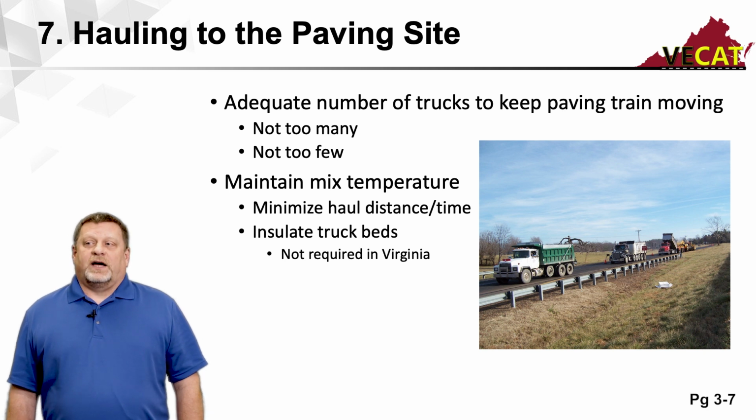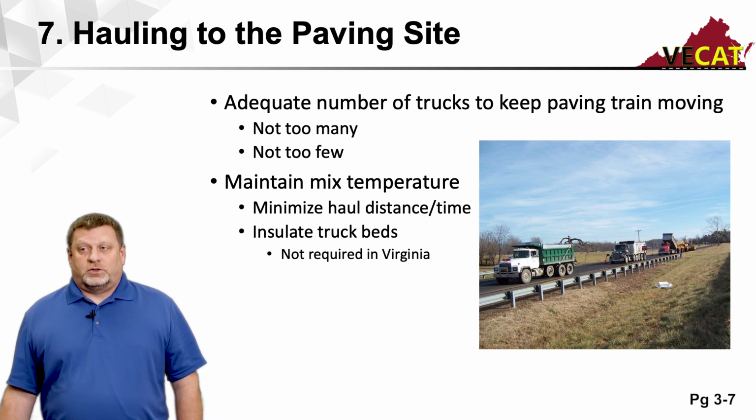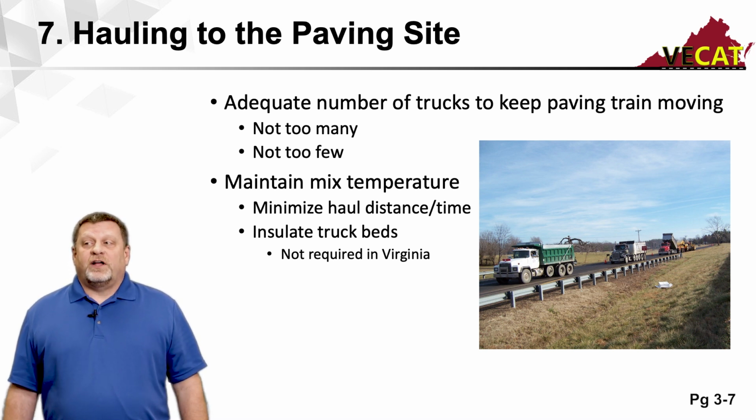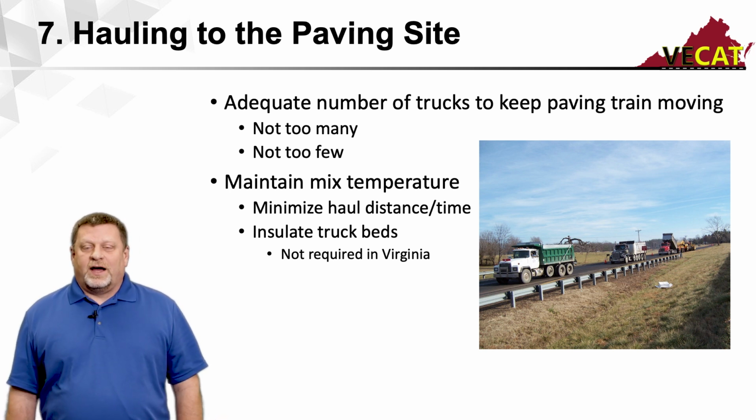Hauling to the paving site. Here we talked about how you don't want too many trucks and you don't want too few trucks. Too many means you'll have multiple trucks in front of your paver. That's not a good thing. Mix is cooling off, and you're paying for trucks to sit idle. That's never a good thing if you're the project manager in charge of this project.